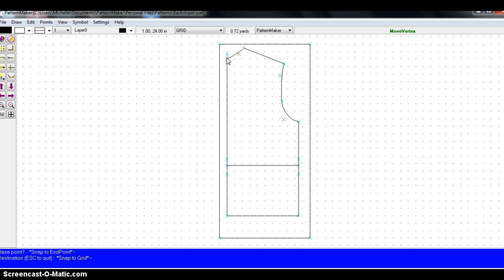Now, to put this point on the grid point, we did Snap to Grid, and select the point with the mouse. Refer to the mouse coordinates in the status bar up above. See right up here? Well, it moves because I moved the cursor, but when it is 1:24, we can either click Enter or left click with the mouse, either one. Now, to get out of snap mode, use Control F1.